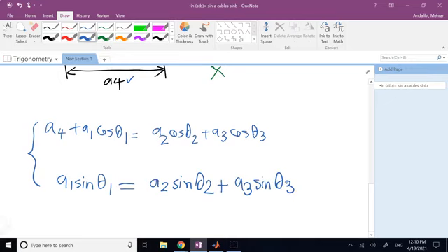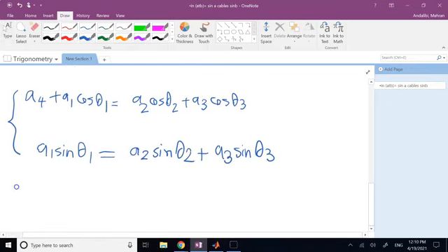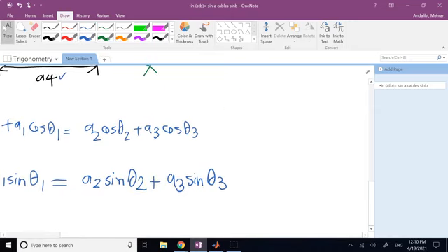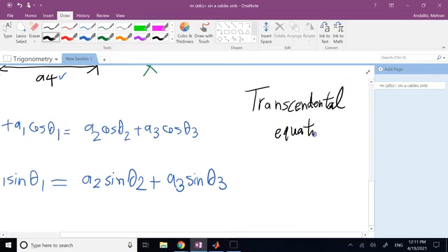Well, clearly here I'm looking into two equations and two unknowns. They are algebraic, but the thing is these are nonlinear in terms of theta 2 and theta 3. I'm not directly looking for thetas. The terms that are involved are their sine and cosine, and these types of equations, in the literature, we call them, let me use all simple letters, no cursive, transcendental equations.